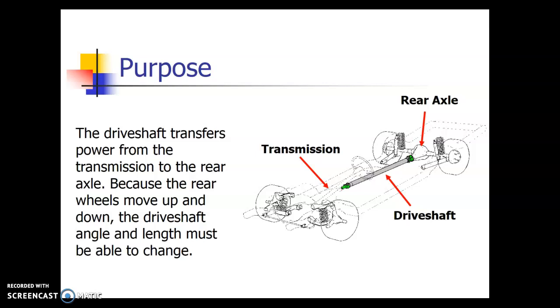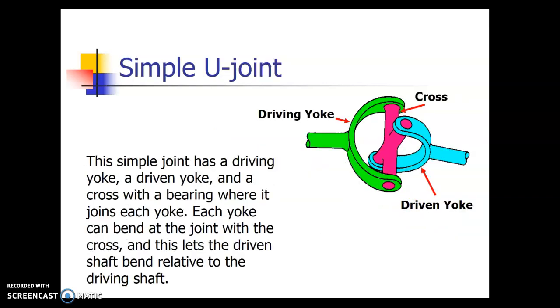So first we're going to talk about a rear-wheel drive platform vehicle, and basically you have this drive shaft, also known as a prop shaft. This is what connects the back of the transmission to the differential. This drive shaft has to accommodate different heights and different lengths. As we'll talk about, it does this via a simple U-joint. Well, it's one component that helps do this.